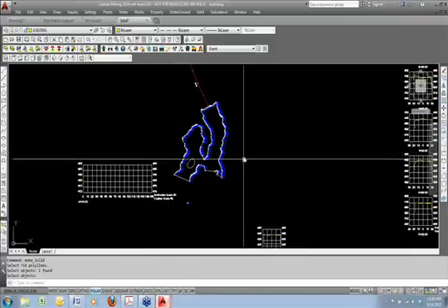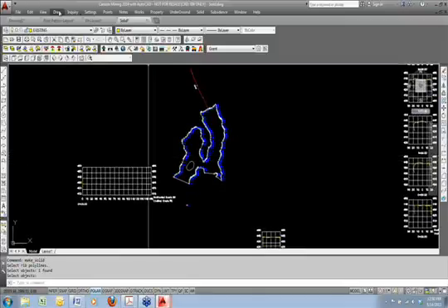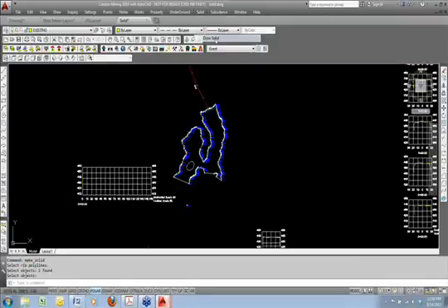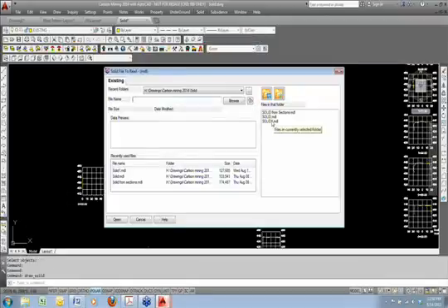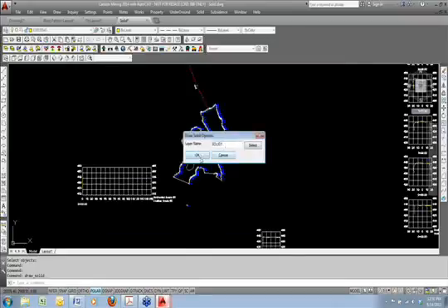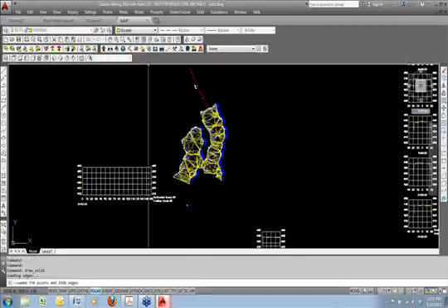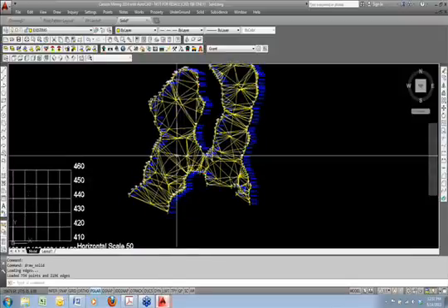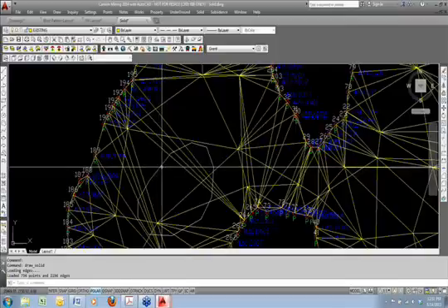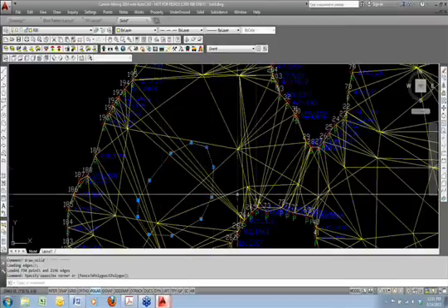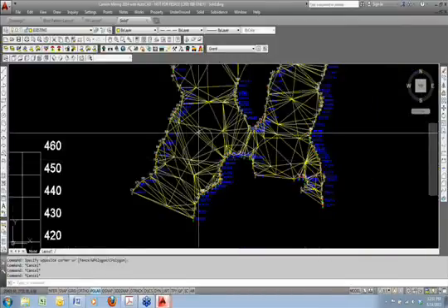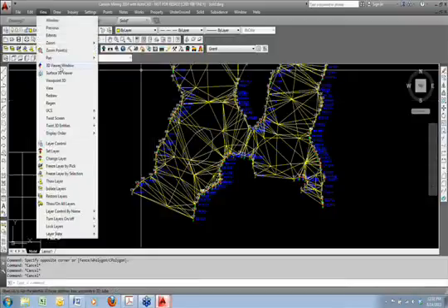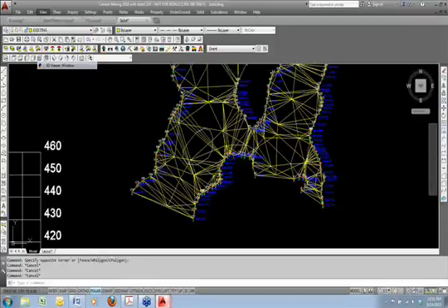Since it's written it, it's a separate file. And now we'll go ahead and draw that solid. Go down to draw solid. And there's solid 1. It's an MDL. Put it on layer solid 1 and drew it. It also handles internal polylines. So this is an internal polyline that I've drawn, also 3D, and that would be an exclusion. So that could be a hole in my solid. So before we view that, well, I guess we'll go ahead and view it first, and then I'll remove it and recreate it with that hole. Go to my 3D viewer window.